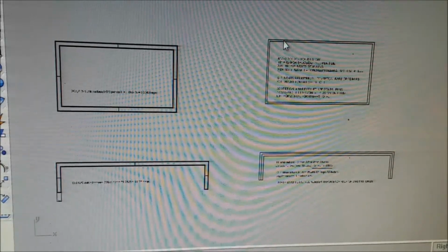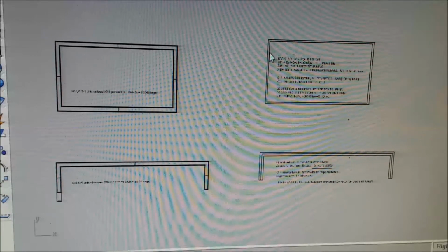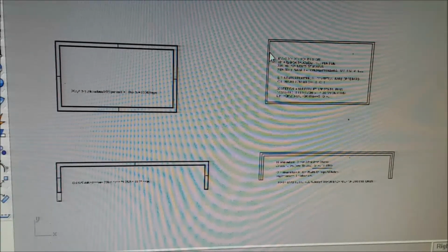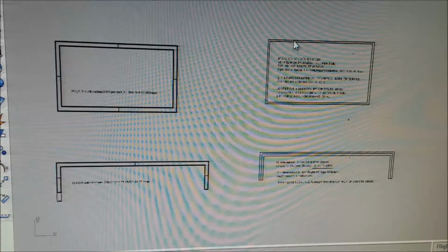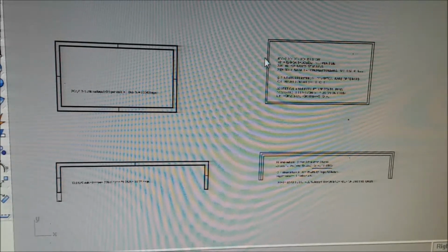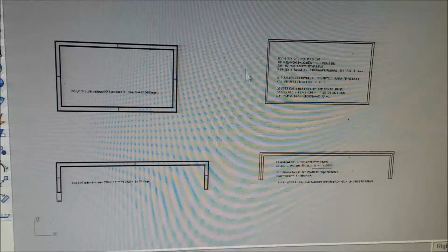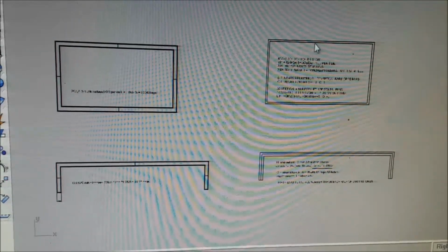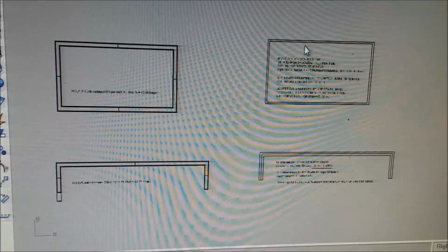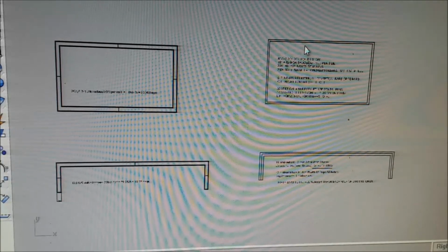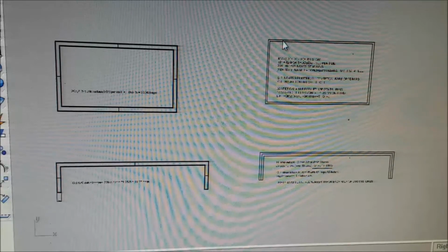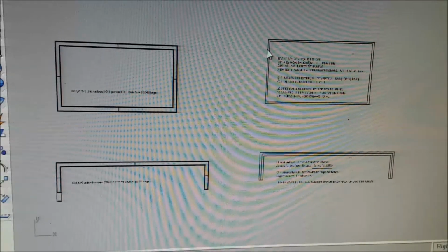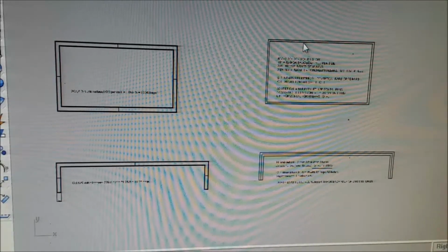If I put a bar here, start off with a full bar, and I cut off 90% of the bar, that is the beginning of the next bar, and there'll be a piece left. It may go up here in this corner. But as you go across here, your splices on your bars don't match up, because you're constantly changing lengths off the end and making them the start for the next bar.